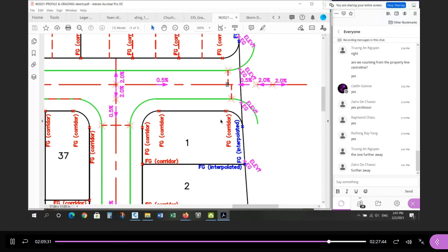The low point station is here, not here. Okay, I've drawn it. There's a choice to be made. It's always the one furthest away from the intersection. So you can ignore this one. Okay, so I snapped this point to the center line of the road. I snapped this point to the edge of pavement of the existing road. And then I snapped these 2 points to the end of these curves. And that's where the low point. Which one? The one further away. So ignore the one closer.